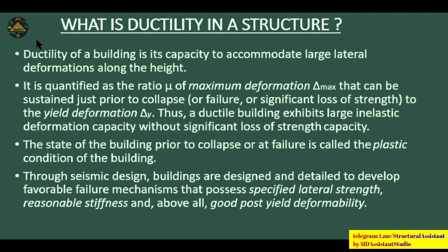After that, we come back again to ductility. Basically, what is ductility? Ductility is the capacity to accommodate large lateral deformation along the height. So it is quantified as the ratio mu of the maximum deformation that can be sustained just prior to the collapse.